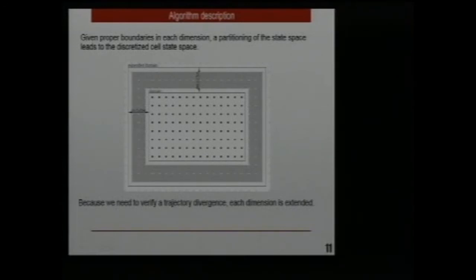For example, in MEMS you have pull-in, or cubic nonlinearity with a negative cubic term, you have an attractor at infinity. So you need to take care also of what happens outside your given window. And so we enlarge the domain a little bit and consider this as the escaping attractor in some sense.